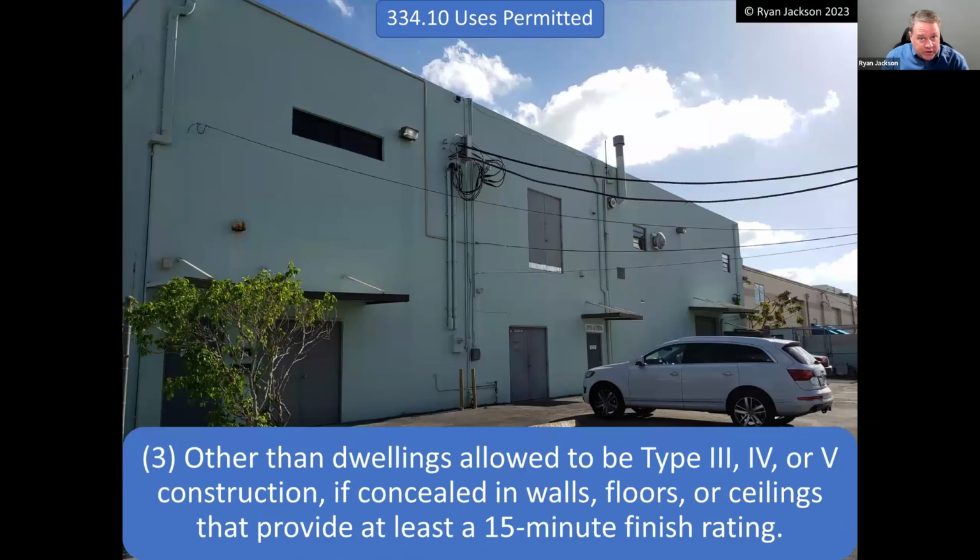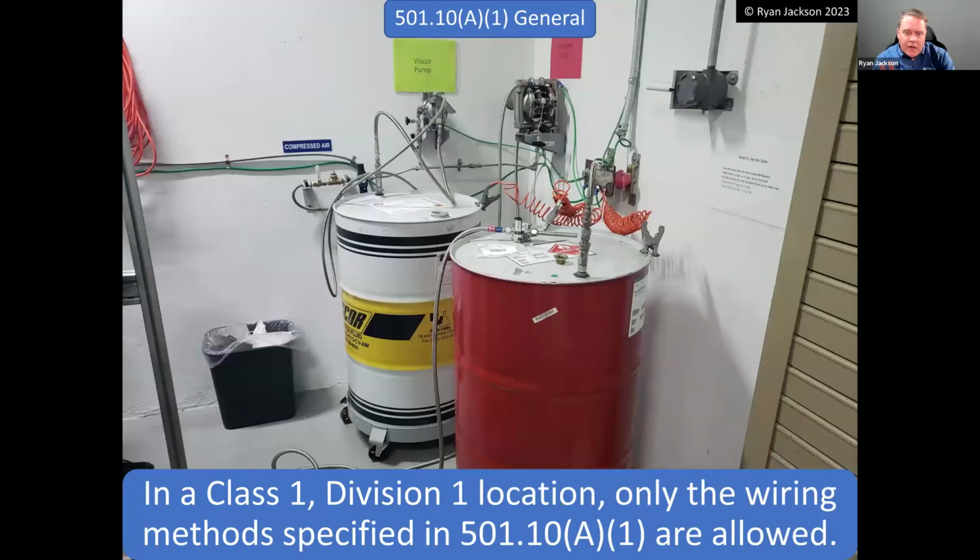In other than dwelling units, so commercial buildings, can you use NM cable there? Well, yes, if it's allowed to be type 3, 4, or 5, and it's concealed behind a 15-minute finish rating. Again, the combustibility issue. So we want it behind drywall, right? We don't want it out there where the flame spread and smoke development is just going hog wild and lighting everything on fire.